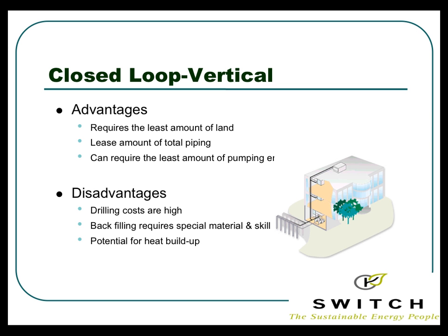As we get a bigger system, bigger home, bigger building, we need more water per ton of refrigeration effect. Climate conditions can limit usage, of course, on surface water. We have environmental concerns more so with surface water with, say, the Cataraqui Regional Conservation Authority, the Ministry of Fisheries, the Ministry of Natural Resources might come into play when we're dealing with surface water systems, open loop systems. And then the big one is fouling becomes a factor when we're dealing with surface water, open systems.